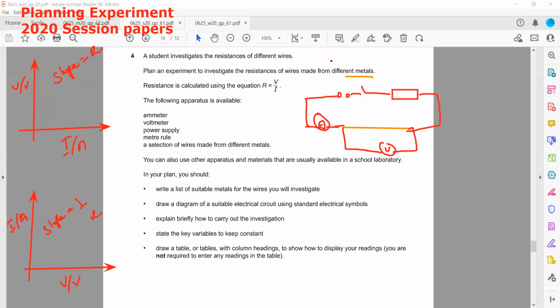So it means if two wires are there, say wire A and wire B, because wire A is having a steeper slope, A's slope is more, it means its resistance is low. But for B, the slope is small, so it means its resistance is high. So whenever current is on the y-axis and voltage on the x-axis, the slope is always the reciprocal of resistance.